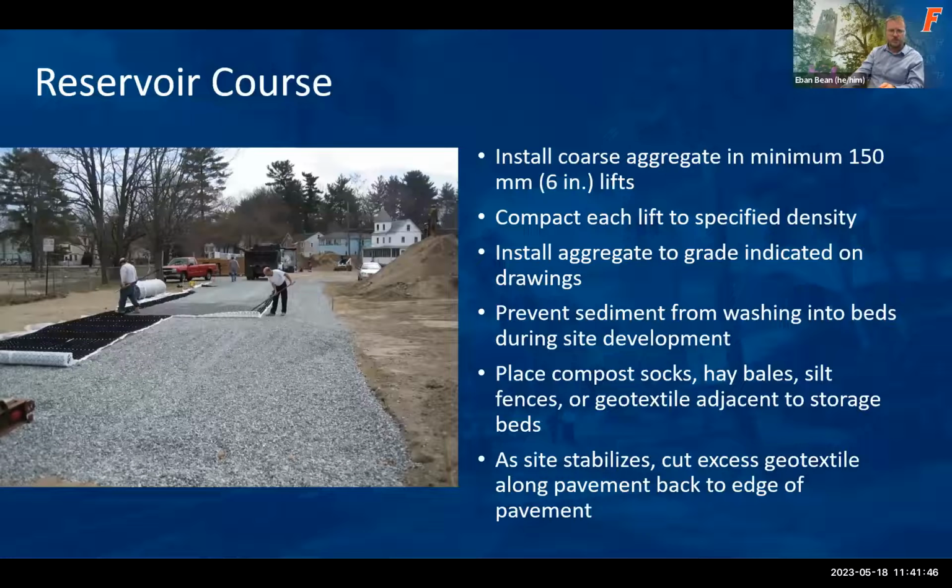A couple of things about installing the reservoir course. You want to install it in about 6-inch lifts. This allows it to settle, and you can compact each lift so that it settles well. You want to prevent any sediment during construction from washing onto it. This is a really vulnerable situation. Think about this photo, where you've got a stockpile of sediment. If you have a storm event, it's going to wash onto the permeable pavement, and you're going to need to clean that out and restore it.